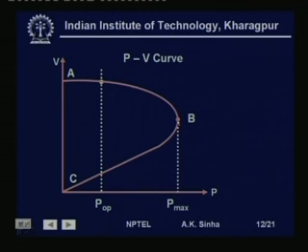The slope is very large at this point, and this point B is the maximum power of the load that we can have. This, basically for a constant impedance load, is going to occur when the load impedance is the complex conjugate of the line impedance or the transfer impedance between the source and the receiving end.